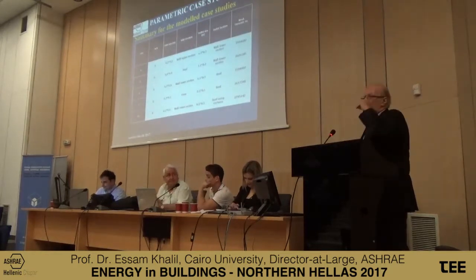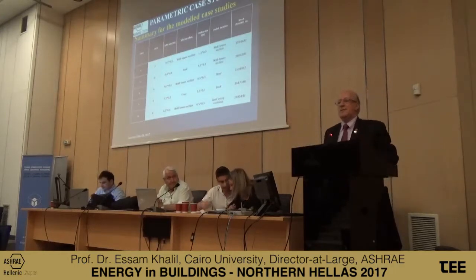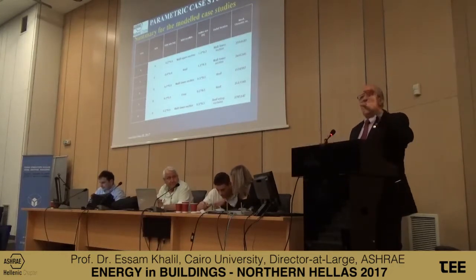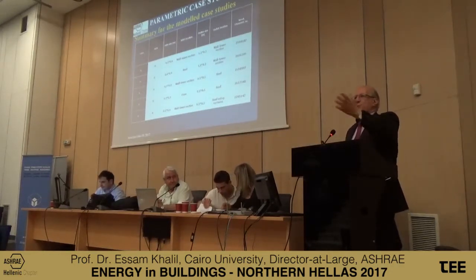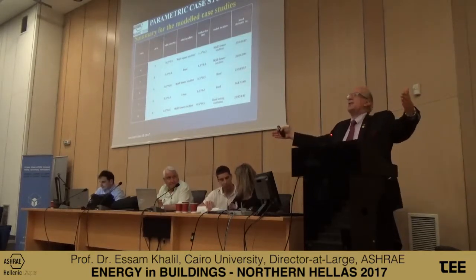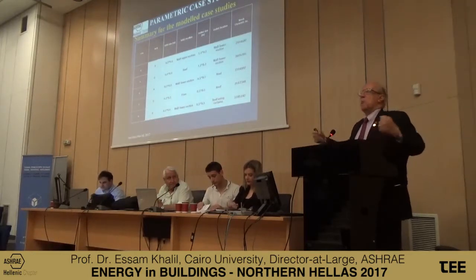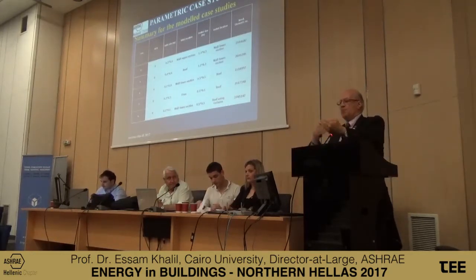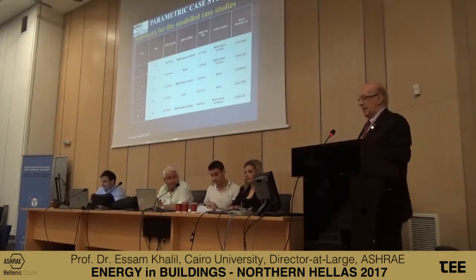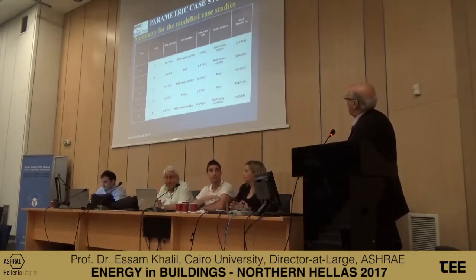You know, when I go to design a project for any client, I specify the value of air change rate at 6, for example. The client will feel that the fans we are putting are large. So I said, why? This is more money, it's more energy. So you have to discuss and try to explain why we are using these air change rates.